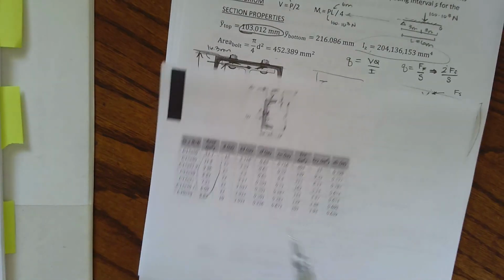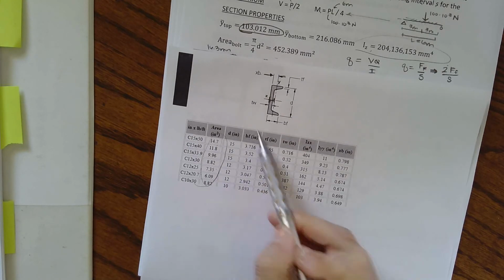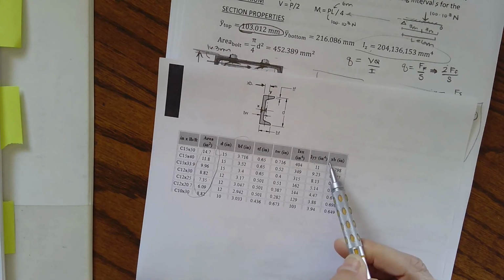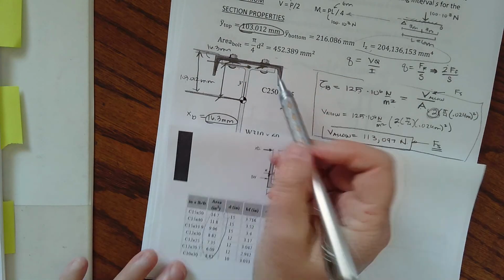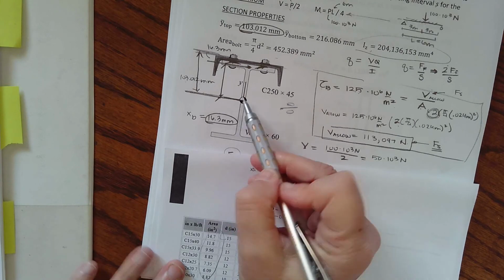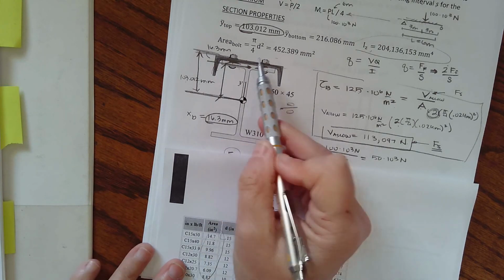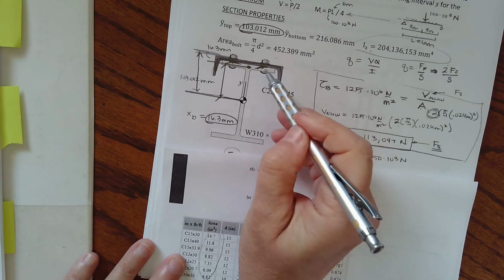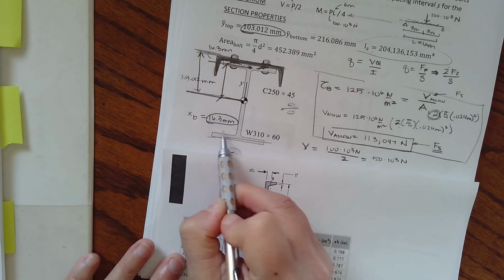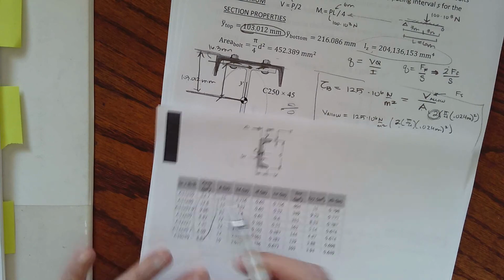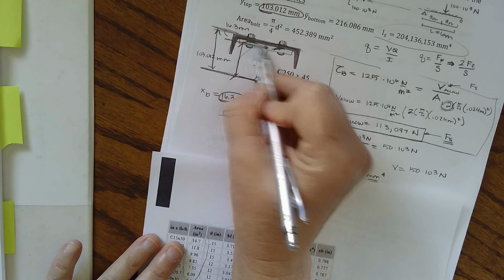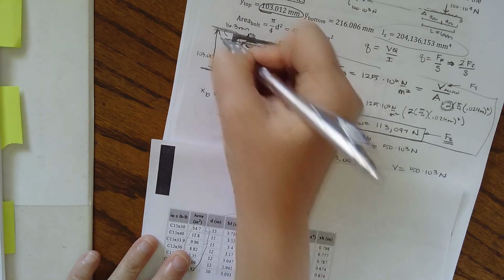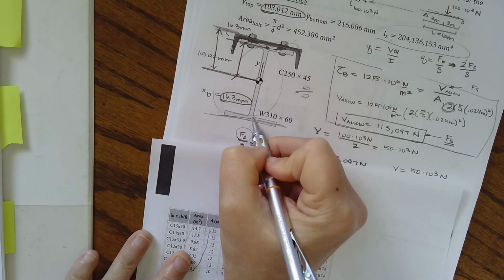But that's how you can use a steel table if you're given these sections, is you can get their areas, you can get their dimensions, you can get to the centroid, their moment of inertia. You guys aren't doing this, but you could. If this is a built up section, where is the centroid? I have to find the centroid from the bottom. So I'm going to have the area, which I can get off of here, times the distance, which I can get, that centroid distance, plus the area, again off of a chart, times its distance from the bottom, divided by all of the areas to get y bar.